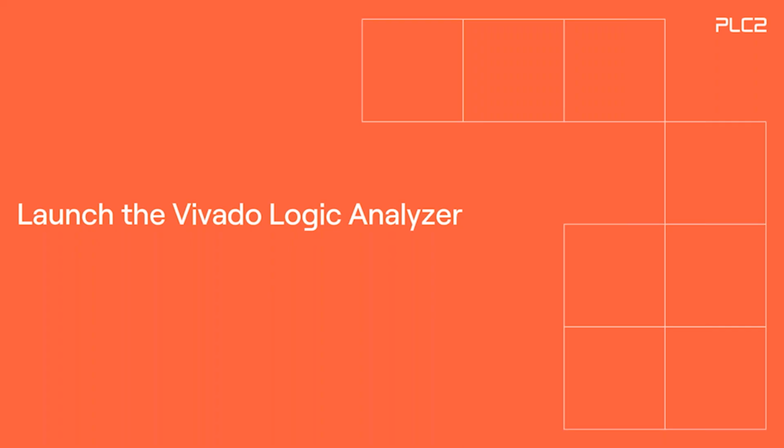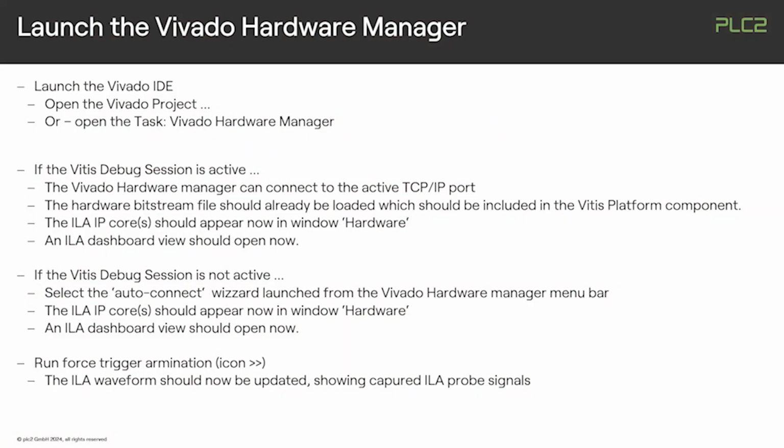So what you would like to get first of all in your context, then you can go back to the Vivado design, where the prepared project, as we showed you before, is compiled and implemented. We have our bitstream file. And in this context, you can then open the Vivado hardware manager.